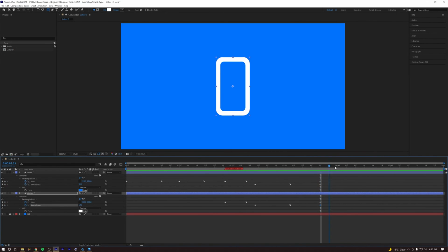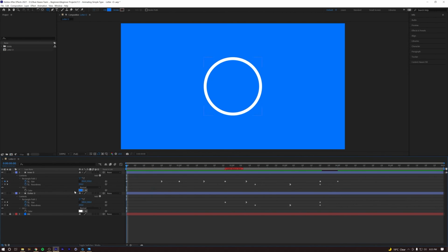And then if you go back here, say to 4 seconds right here, what we need to do is get it back to its first shape basically. So 450 by 450 was the first shape, the inner. So if you go 450 by 450, click off. I know you're not going to see anything right now, because we need to go back here again and see this one was 250, the roundness. So the roundness needs to be 250. So if you go here and go 250, let's click down here, it's going to go back to a circle,